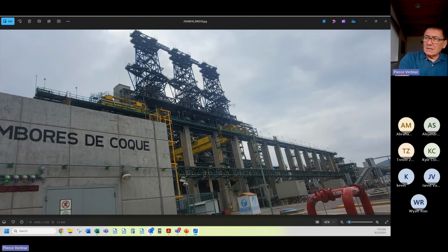And once the coke fills up the cylinder, these towers have winches on them that lower a water jet cutter into the cylinder. First, they lower the water jet cutter into the top of the cylinder with the water jet pointed down, and the water jet drills a hole all the way down the center of the coking tower.